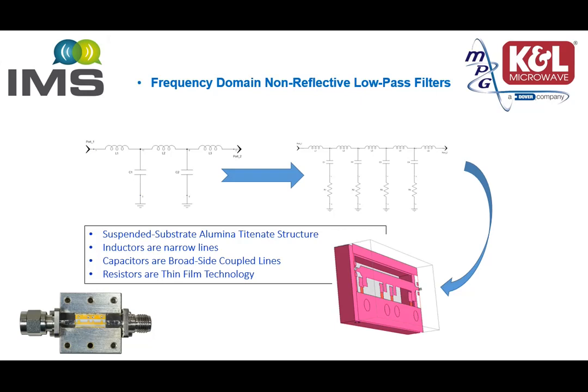The inductors are the narrow lines. The capacitors are realized as broadside coupled lines, so the energy goes through the PC board. And the resistors are thin film technology. It's called suspended substrate because the substrate is suspended between two layers of air.